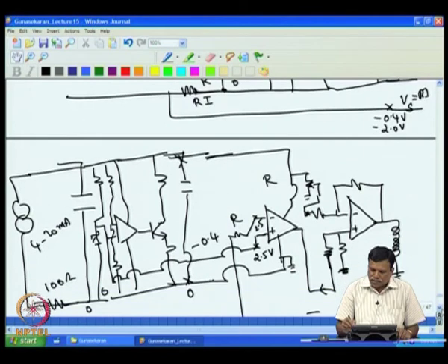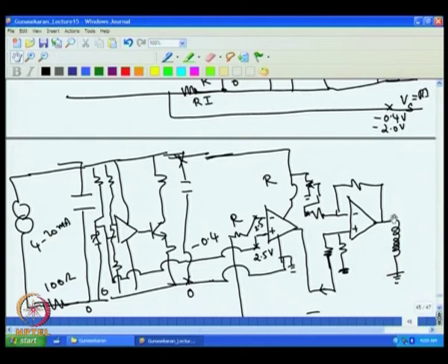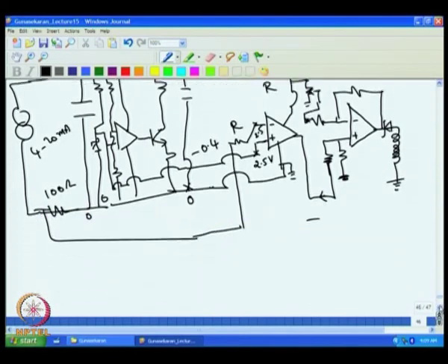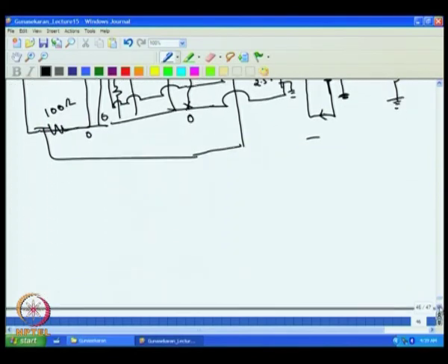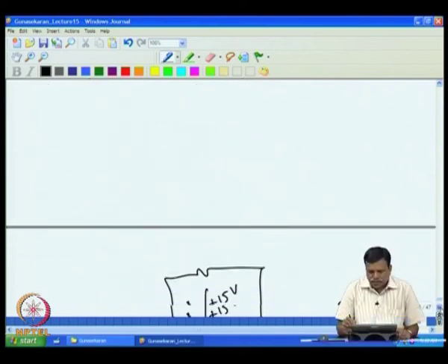So for example in this case there will be some output voltage. If you do not want that output voltage, then we have to make sure that the extra voltage, whatever is coming, is not driving this. One popular way of solving that is to put a Zener, so that the minimum voltage coming from the op amp is dropped across this Zener. So this is one of the important observations we have to make in terms of usage of operational amplifier with single supply.